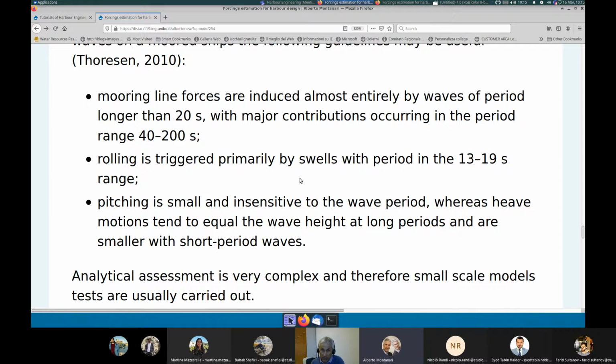You have to account for the scaling effect, which, for instance, may bring viscosity to come into play in the lab, because you compress the harbor into a small pool, so the viscosity of seawater becomes more important, and then you have to take this into account.